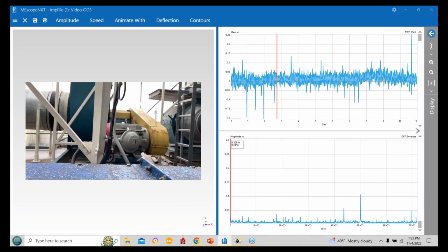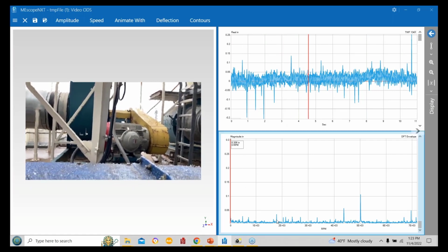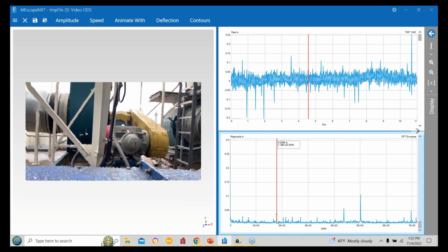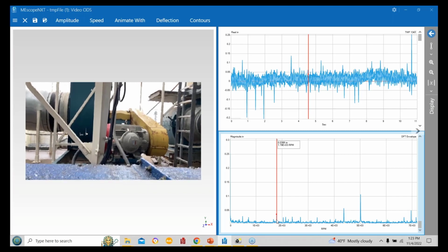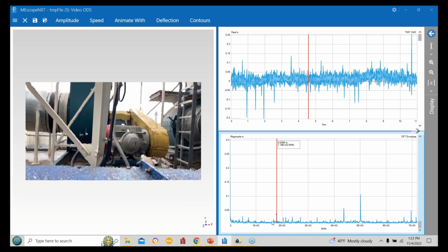There we go. We got a time waveform at the top, which you should know is a combination of all the frequencies going on. There's a couple rotating frequencies. There's synchronous and non-synchronous. There's subsynchronous. They're all over the place. So there's lots of different peaks in the spectrum. If you look down below, I'm going to light this one up. This is the turning speed of the motor shaft. Okay, 1800 RPM, it's 1790 because you get a little slip.